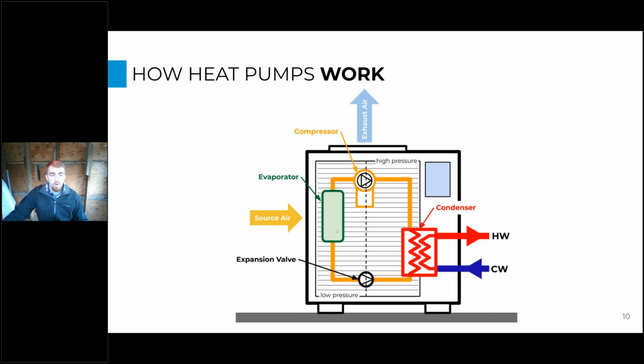So now it's colder than the outside air. So now we're transferring heat from that cold air to an even colder refrigerant. So now our second law of thermodynamics is happy again because we're transferring heat from a warmer medium to a cooler medium. So we have low pressure, really cold refrigerant sucking heat out of the air and then moving to the other side of the loop, warming up significantly by changing to high pressure, and then exhausting that heat out into the domestic hot water.